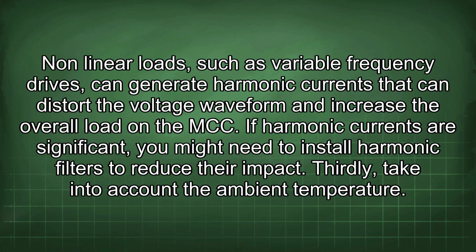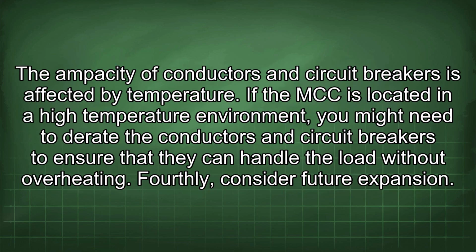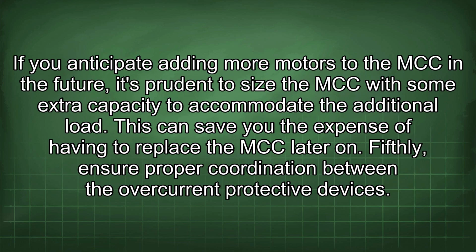Thirdly, take into account the ambient temperature. The ampacity of conductors and circuit breakers is affected by temperature. If the MCC is located in a high-temperature environment, you might need to derate the conductors and circuit breakers to ensure that they can handle the load without overheating. Fourthly, consider future expansion. If you anticipate adding more motors to the MCC in the future, it's prudent to size the MCC with some extra capacity to accommodate the additional load. This can save you the expense of having to replace the MCC later on.